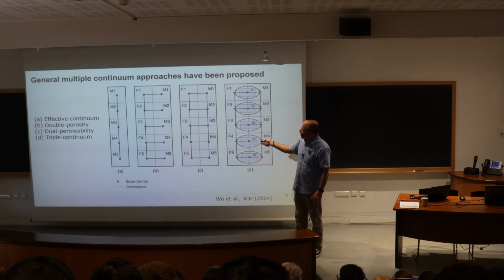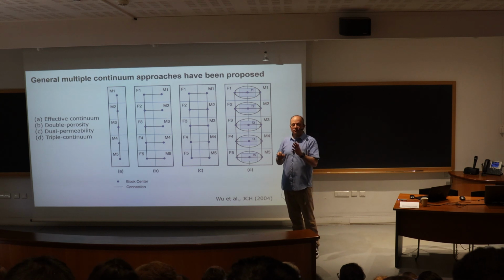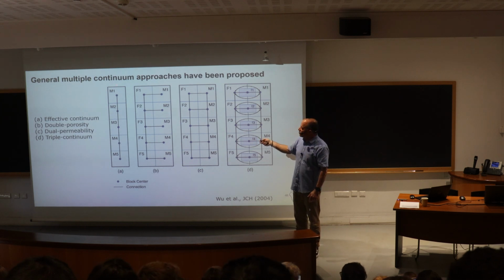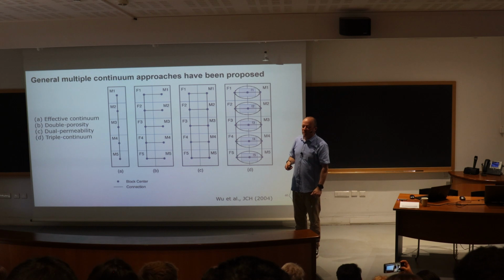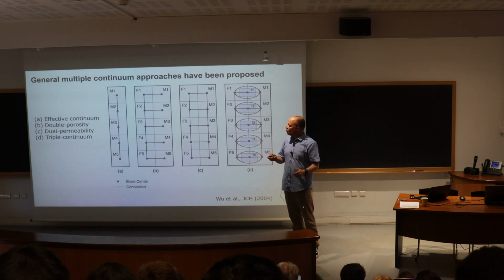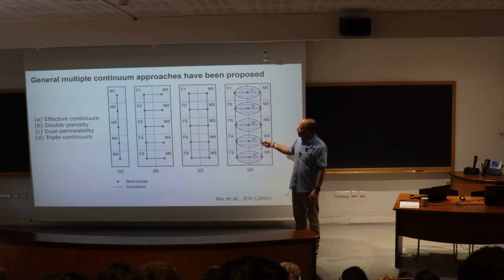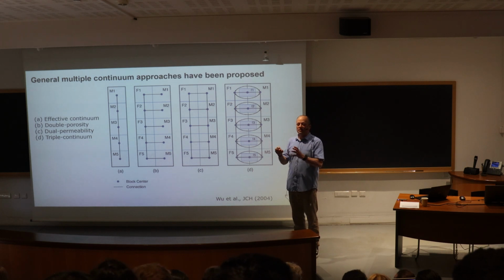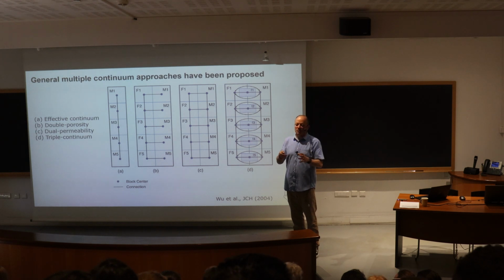So here we would have a single fracture represented as an individual fracture that is in a matrix that is porous and potentially permeable, or it could also be an equivalent porous medium approach or continuum approach where we have, in this case, matrix and fractures represented by a single cell with equivalent properties. So the properties would be lumped properties of fracture and matrix.